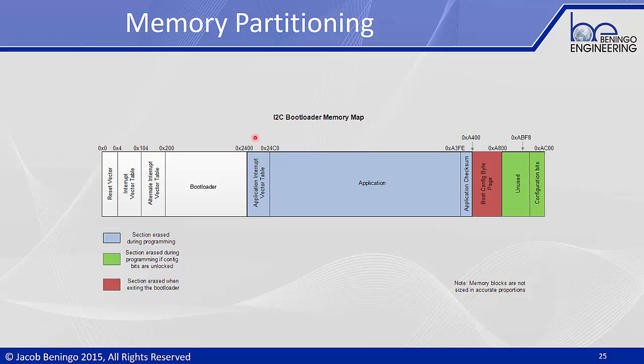Typically what you find is that flash space is organized into pages and sectors, where a page is usually the smallest number of bytes that you can erase at a given period of time. So you may find that 256 bytes is the smallest amount of flash space you can erase at a time, or maybe even a sector is the smallest amount that you can erase. Sometimes flash controllers only have a sector erase, which means if you're going to erase something, it's 4K bytes of space that you're going to erase. So you need to really dig into the data sheet for your flash space as well.